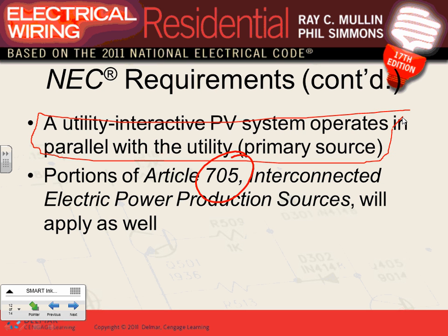So the disconnect that comes from a solar photovoltaic system, my service is right in the other wall, right at the service. I have to see another source of power coming from the solar on a roof, and the disconnect is located on this wall. Anybody knows why? Because the firefighters walk in to shut down the power, not knowing that there's another source of power there. They need to be able to see that there's another source of power. Okay.